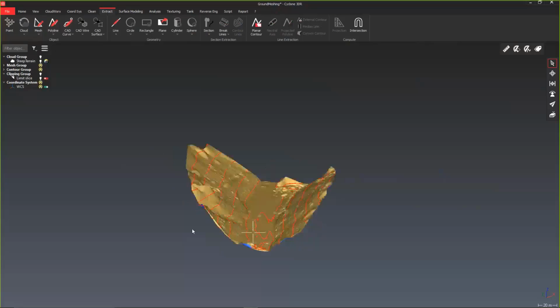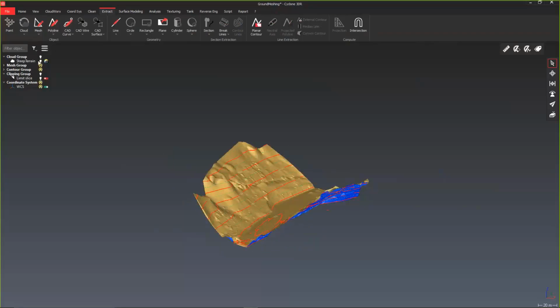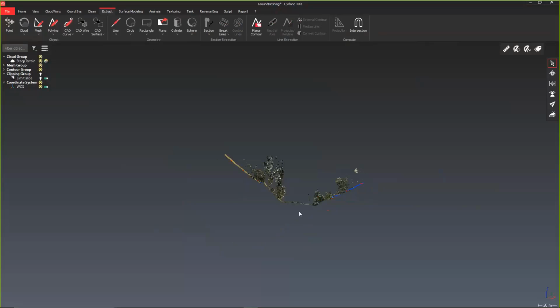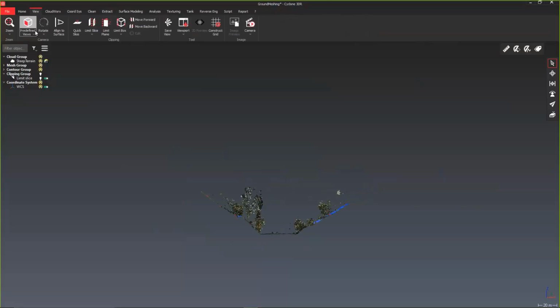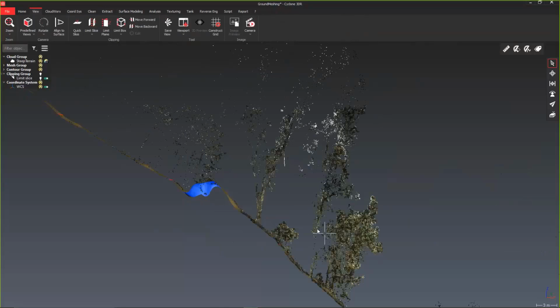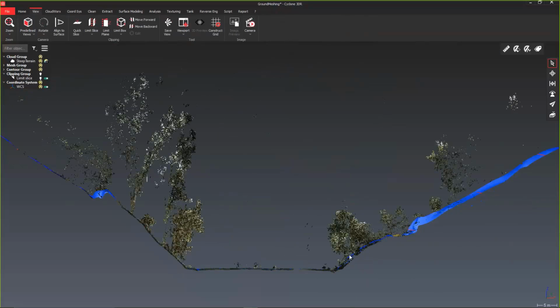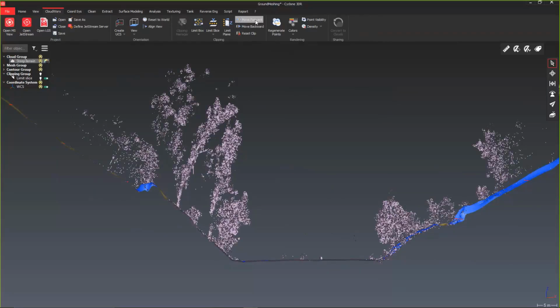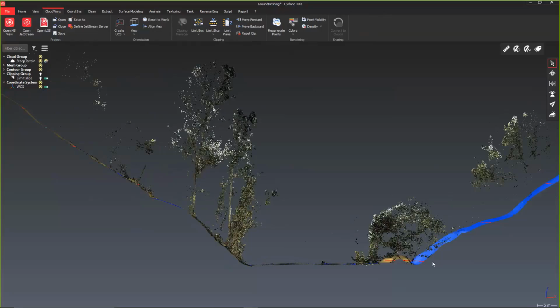And just as an extra check, I can turn that cloud back on, and then turn on that slice again, and I'll go to my view and front, and let's look, how did the mesh do? Looks like it's doing a pretty good job to me. And of course, if we wanted, we can move forward through and see again how the mesh did all the way through, right?